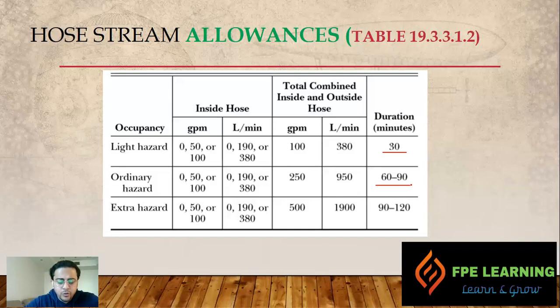For the inside hose, we are just going to talk about the flow requirement. Even in our hydraulic calculation software, let's say Elite software, if you want to add, let's say, 100 GPM for inside, we are not going to care about the pressure. We are just including the flow. Let's say our sprinkler system needs around 350 GPM at some certain pressure. So we have to add 350 plus 100 GPM, which is 450, at the pressure requirement for the sprinkler system.